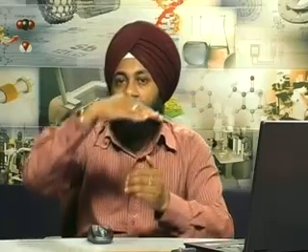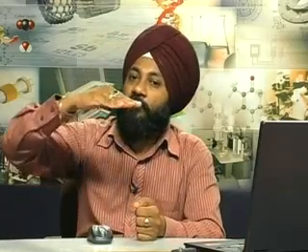Now, depending upon what material we are going to machine and what the material of the tool is which we are using to perform the machining operation, that is going to affect the wear rate, or the rate of tool wear. Moreover, the tool shape. Suppose, under the conditions that lead to tool wear, one edge or one surface of the tool rubs against the freshly generated machined surface. If we are able to provide a proper relief angle or clearance angle, so that this surface is not rubbing against the workpiece surface, then by avoiding this rubbing action through a particular angle on the tool, we are able to control the tool wear.